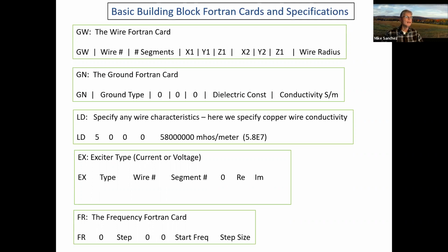Then, having put in the number of segments, you have to define the antenna in 3 dimensions. Today will be 2 only, but in general, you'll have to define your antenna in fully 3 dimensions and specify each wire end point. So you'll have to specify an XYZ for one side of the antenna, whatever wire you build.